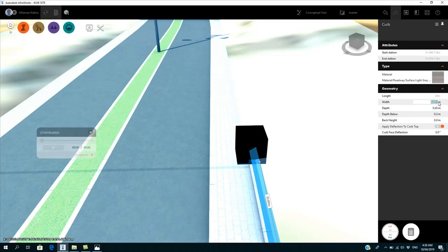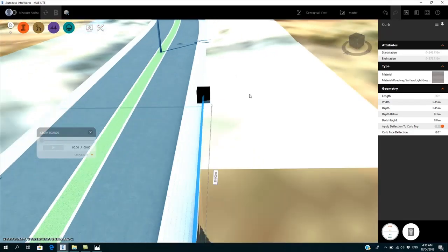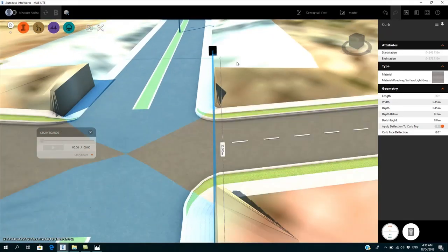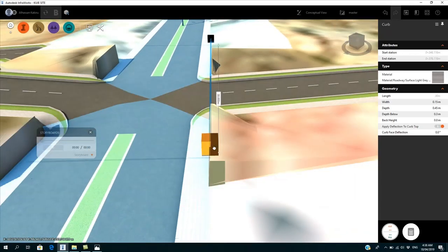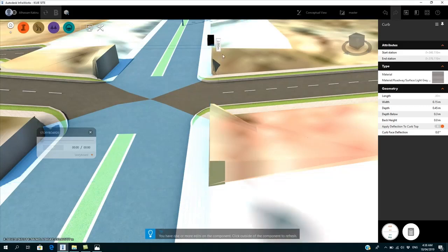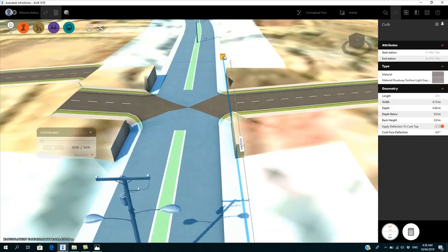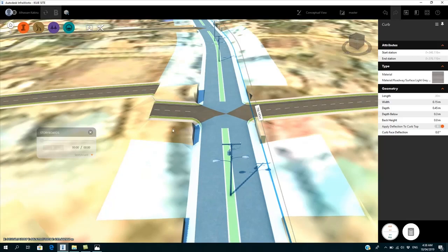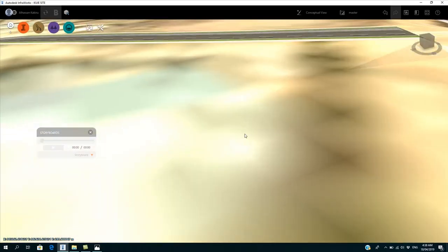And I did this curb line to have a width of 0.15, that's 150 mm, 15 cm. Then as well I can update it to change. So irrespective of making any mistakes, you can as well replace those mistakes with the actual things you want. So define the curb line to the start and end of the road, to complete the site for the curb activities.